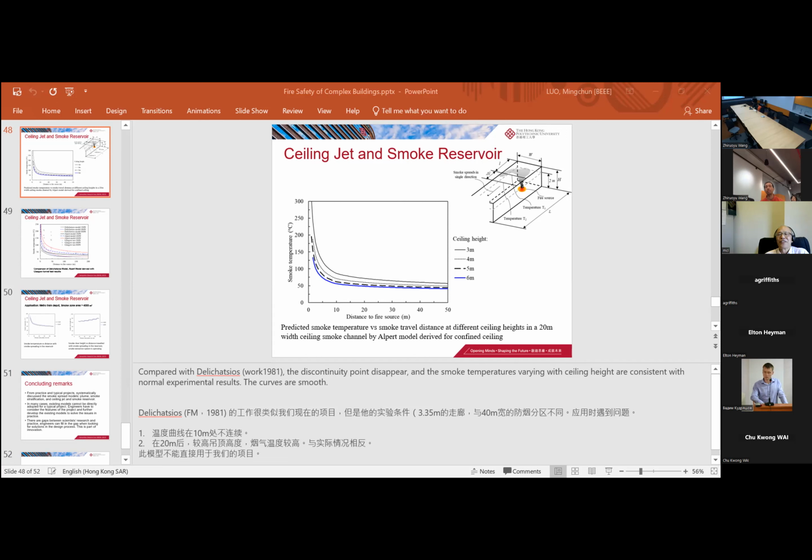So you still need the plume models. This is very basic, and it is where you start with the project. With the CFD model or zone models, you can do the detailed analysis to tell the authorities this design is okay, and that people will be safely evacuated based on this condition, but not for design.